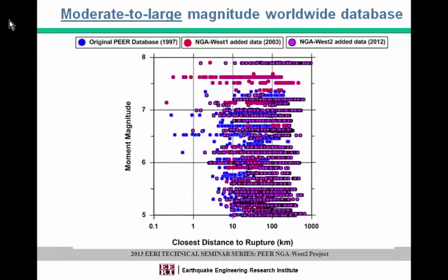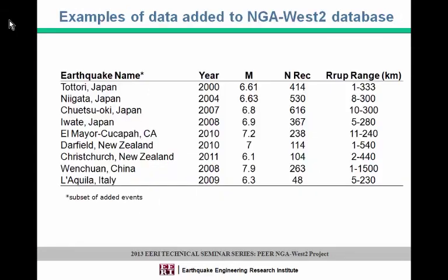One important feature that you see now, magnitude 7.9, we have another earthquake, Wenchuan in China, which is relatively well recorded, with various efforts that all of us at PEER made, we signed an MOU and so on with the Chinese. We got almost all the data that they had, with 64 aftershocks with very good soil profile. Every one of these takes lots of effort even to get the data, especially foreign earthquakes. We get the data, then process the data. So this is what we have from magnitude 5 to 8, a very rich database.